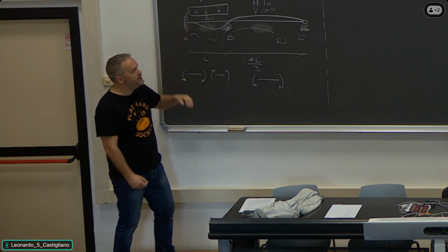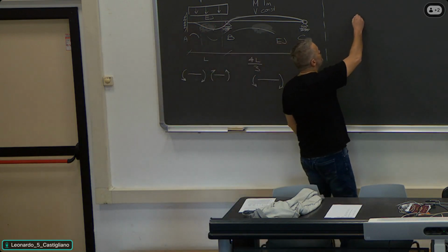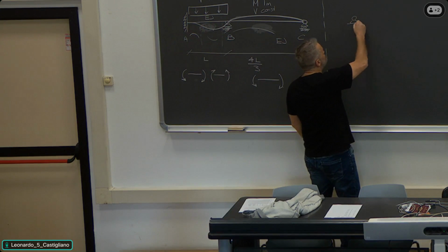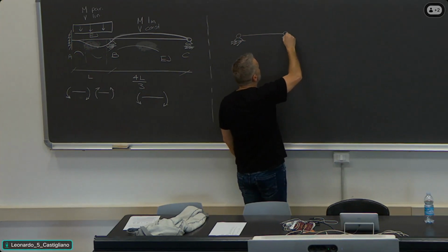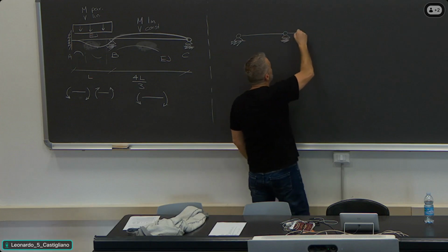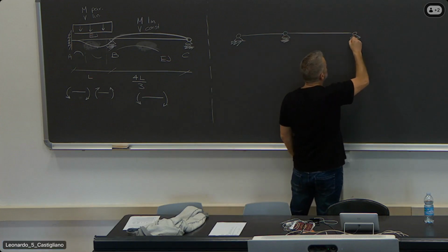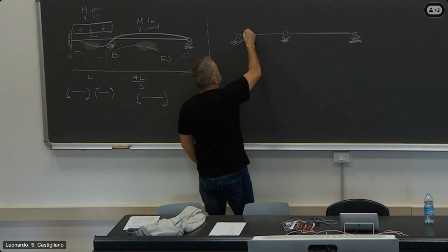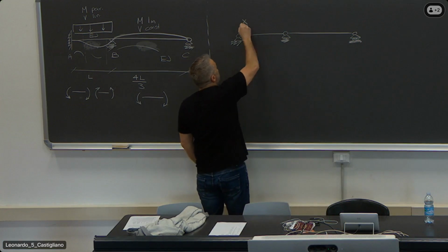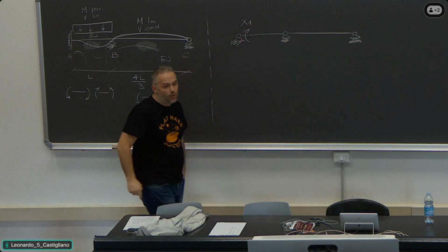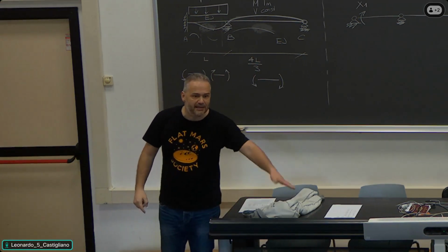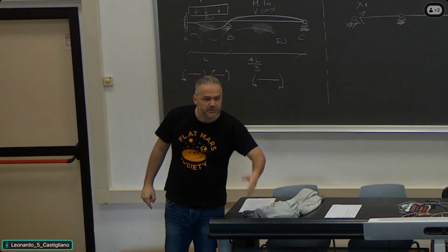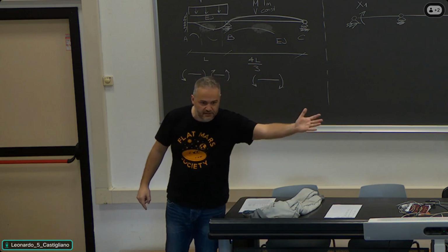Putting all this together, to solve the structure, you need to determine two bending moments, which are here. One is x1, and I draw it only once because it's a moment that is exchanged between the structure and the reference system, the ground, the soil, whatever.